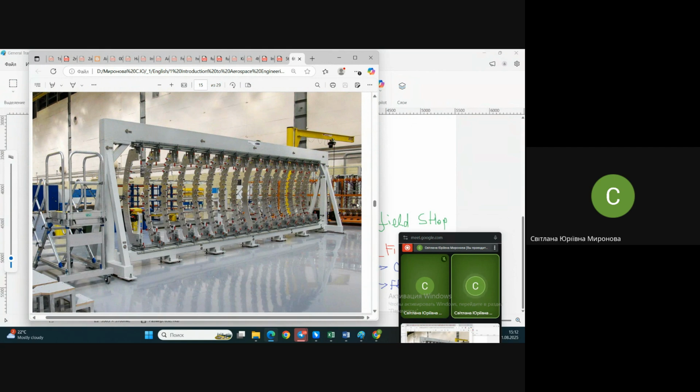And in this case, we use other techniques of coordination, which originally were based on the use of natural copies of the airplane, so-called mock-ups. But not even mock-ups, because people were not able to produce these mock-ups originally, and they don't actually need them. They used cross-sections of mock-ups in different directions, and these are called templates. They provide the coordination of all the tooling for the airplane to be produced, to all the contours, outlines, and so on.